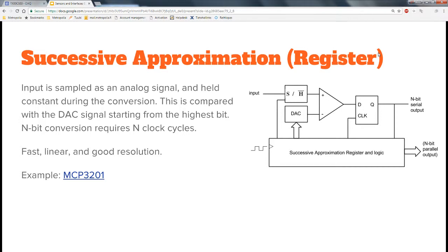This is kind of midway technology, successive approximation. This is the successive approximation register type of A to D converter, where you can have relatively high sampling rate and high precision at the same time. Basically, there is a D to A converter and a digital logic that clicks some bits on the D to A. D to A's are quite simple to make with a high precision.